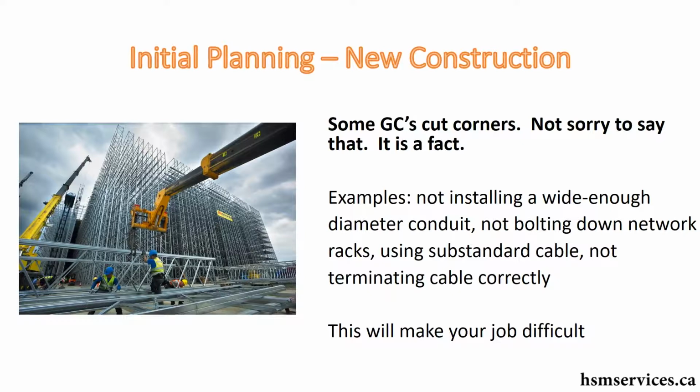And of course, some of them cut corners. It's a fact. Things that they've done, besides horrible delays and damaging equipment: I've had GCs not install wide enough conduit, or use flexible conduit that you can't pull a cable through, not bolting things down, using really cheap Chinese cable, not terminating the cables correctly.